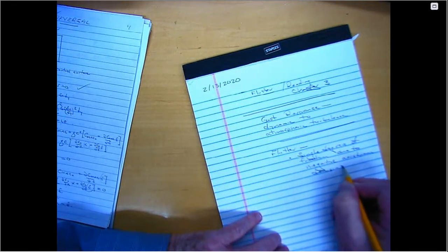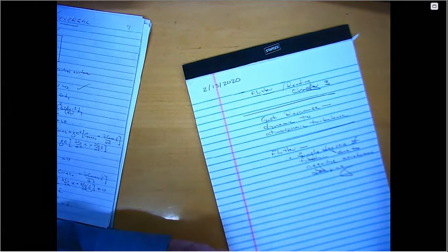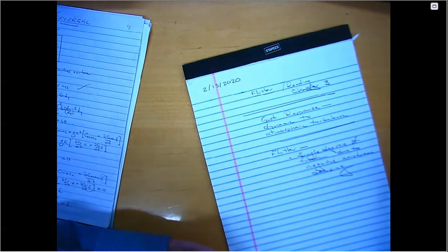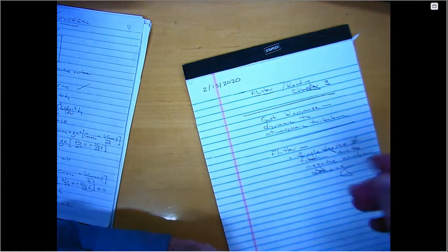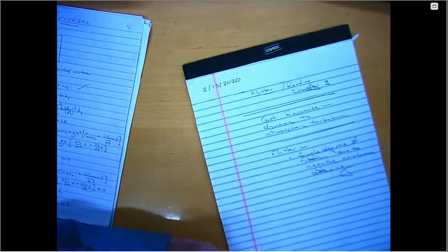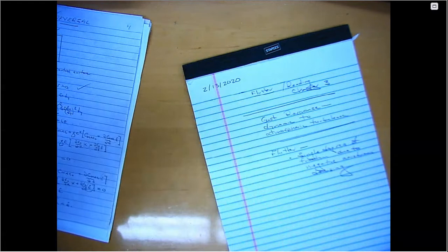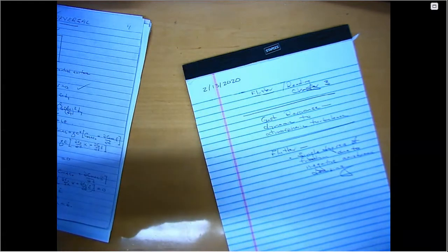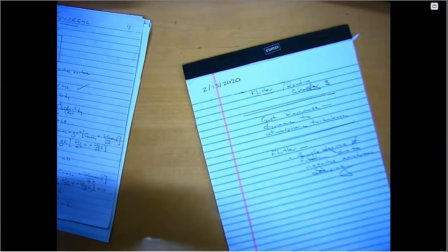That doesn't mean you necessarily can only look at one mode, but what it does mean is you can look at each mode one at a time, individually. If I have 13 modes that might experience this kind of flutter, I can look at each mode separately. Or in the case of turbomachinery, if I have a cascade, all of the blades may be moving more or less the same way, except there's a phase angle in time between the blades, right?